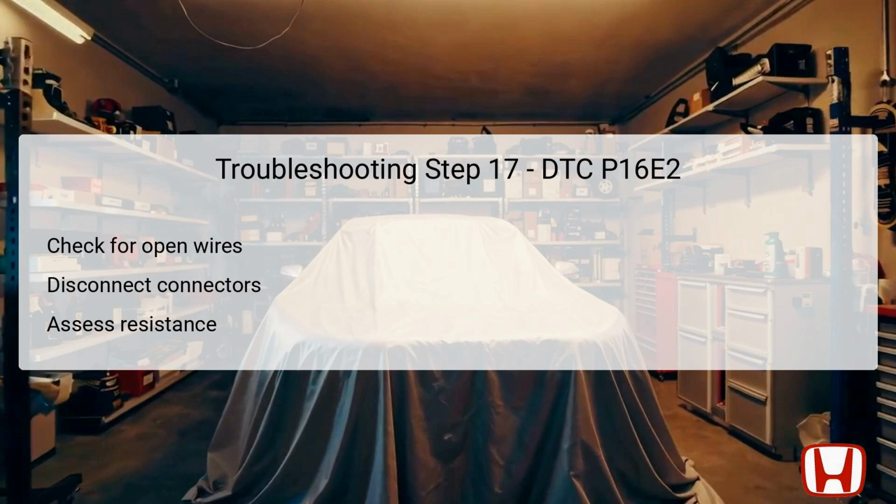Testing once more with the selected parameters, particularly focusing on the alternator's female terminal number 1 against the PCM's number 10 terminal, will allow adequate assessments. If resistance registers at 1.0 ohm or less, it indicates successful communication pathways. Higher values necessitate critical repairs on any identified open wire areas between the alternator and the PCM.